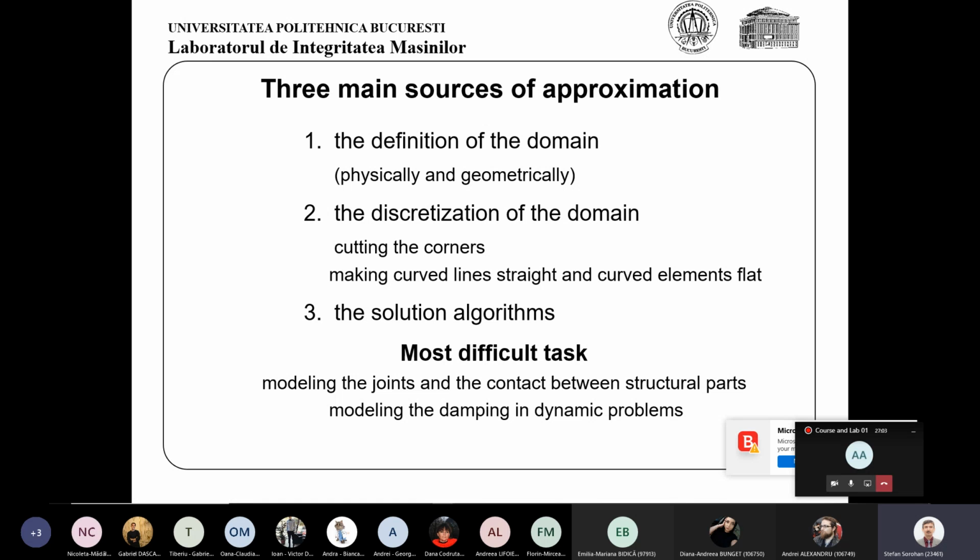But generally, please keep in mind that the boundary condition usually means supports and loads. Supports means that somewhere we have some displacements which may be known or maybe also zero, and the forces are the loads, the pressure maybe also the force. So boundary conditions in this kind of problem are very important.